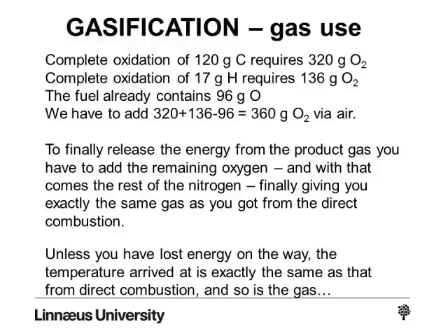There is no difference. You do not upgrade the fuel. You do not change the composition of the fuel. You do not alter the temperature that you arrive at. You do not alter the amount of flue gases. So unless you have lost energy on the way, then the final product and the final temperature after gasification with direct combustion is the same as for direct combustion of the fuel itself.